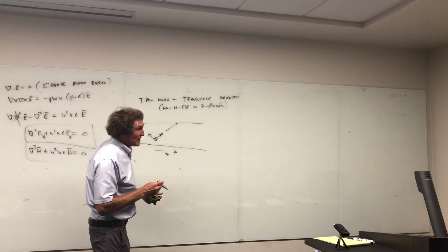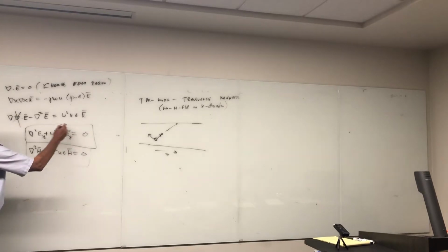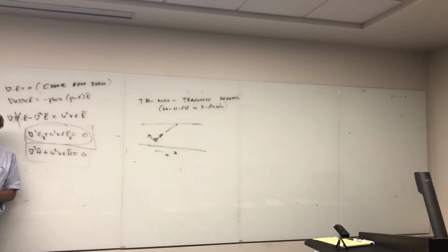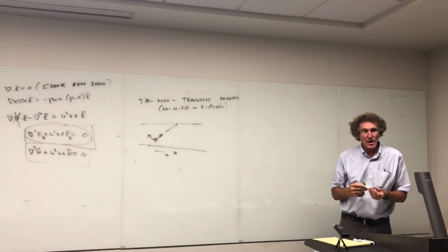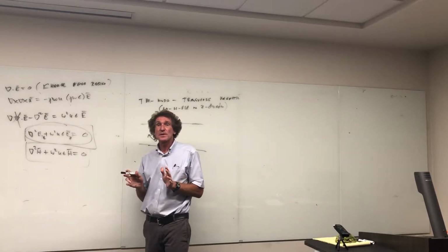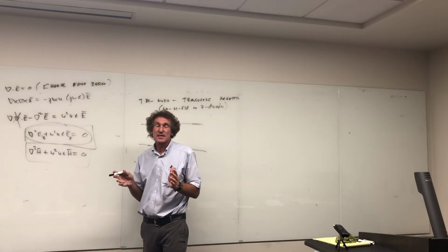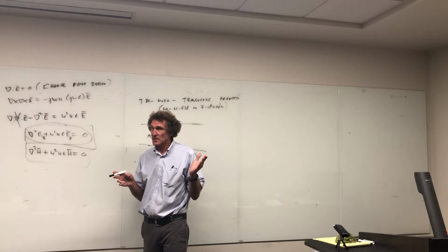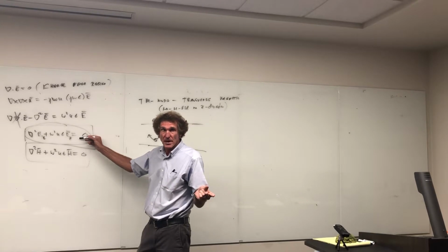So what does that mean? Here's what it means and how come it's nice. If there's no H field in the direction of propagation, we can say there is an E field in the direction of propagation. So now I'm going to solve this. I want you to pay attention, and I don't want to give details that are just there to aggravate you. I'm going to try to be very clear about what you need to know and why. First thing is, you always look for the component that is in the direction of propagation when you do waveguide solutions. Since I said it's TM, there's no magnetic field in the direction of propagation. There's only electric field. Then you solve the differential equation for the component in the direction of propagation.